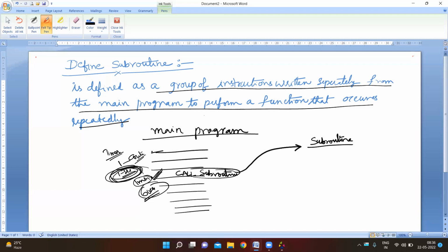So to repeat the 1 second delay 60 times, we just call the subroutine program by the call instruction, and we can shift the program sequence to the subroutine program where the 1 second delay is written. After the 1 second delay program, our program should jump back to the main program.